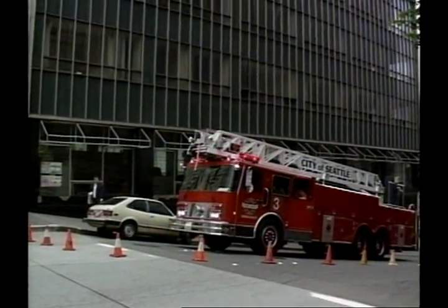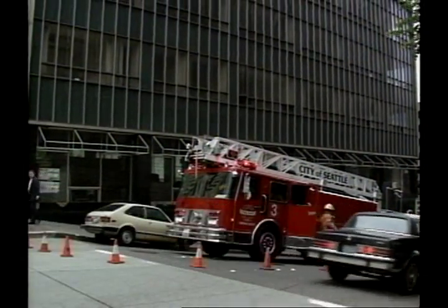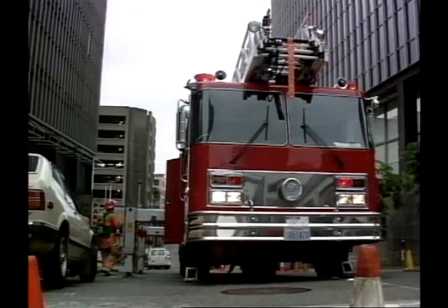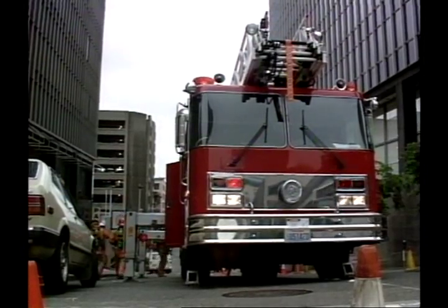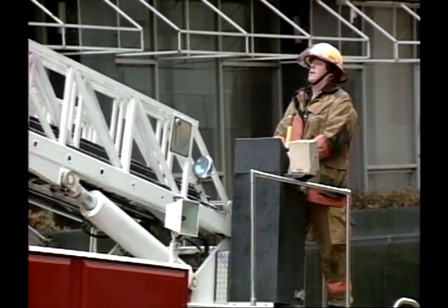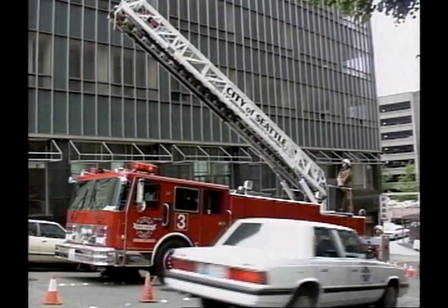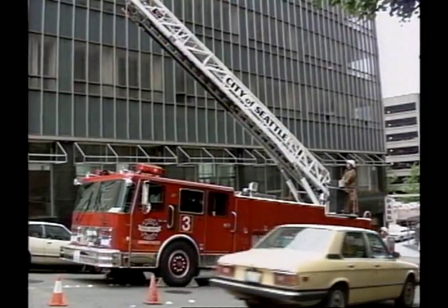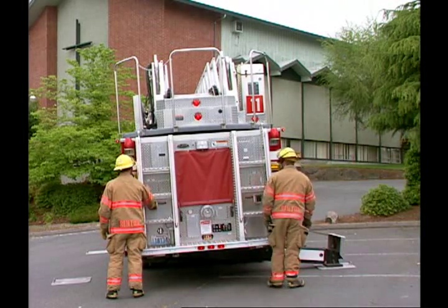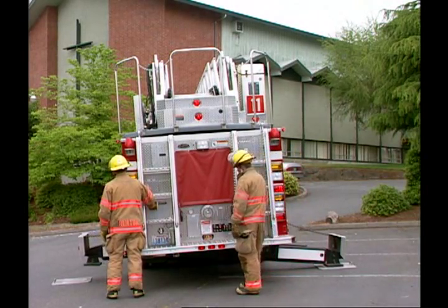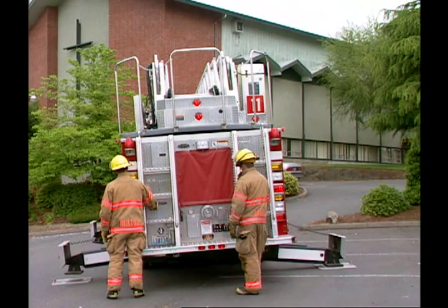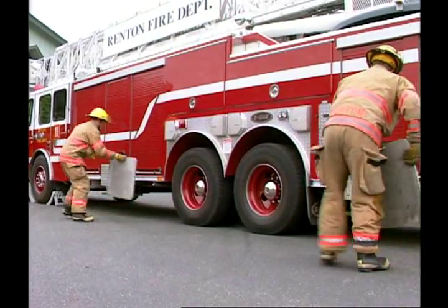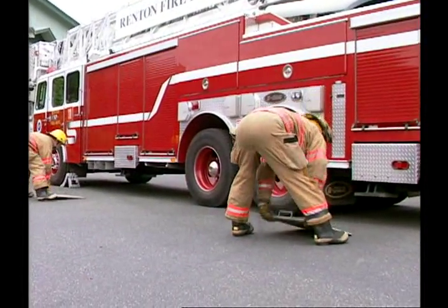In some situations, you will need to position the aerial apparatus on uneven terrain. When this is necessary, it is important to make the apparatus as stable as possible. Keep in mind that uneven terrain will always limit your operation somewhat, because maximum stability is only possible on flat, even ground. There are two ways that the truck can be uneven: laterally, or side to side, and longitudinally, or end to end. Of the two ways, it is easier to correct for lateral unevenness.